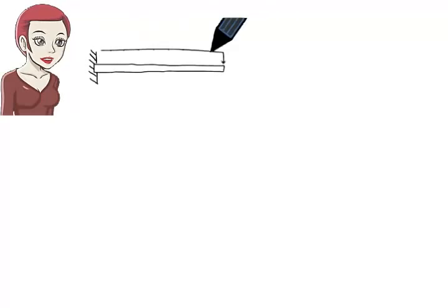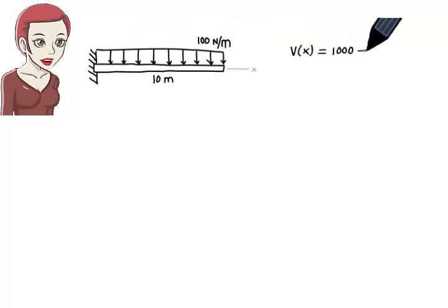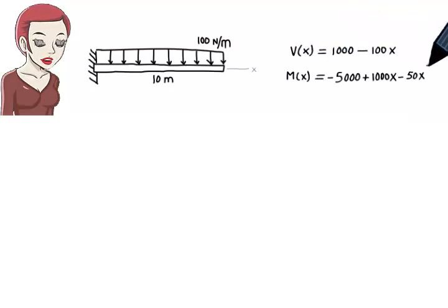The aim of this lecture is to help students learn how to come up with shear and moment equations for beams subjected to various loads. Representing shear and moment algebraically is very useful, as it allows the structural engineer to quickly identify critical stress areas in the beam. In most cases, it may not be possible to write down only one equation for shear or moment for the entire beam.